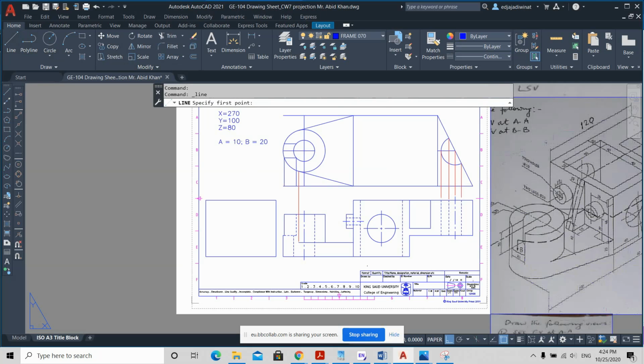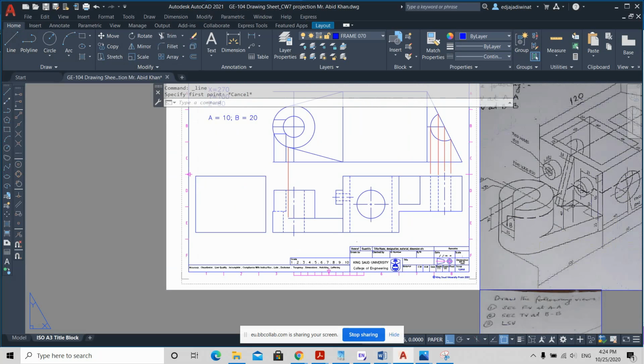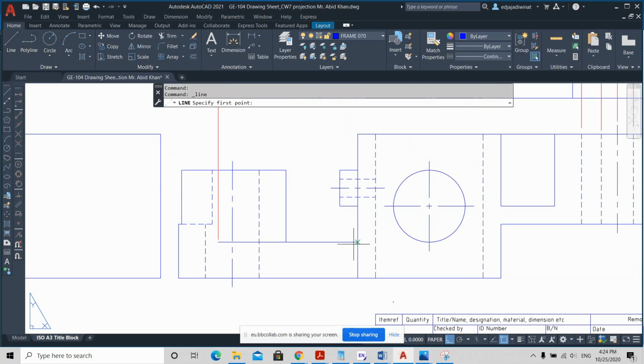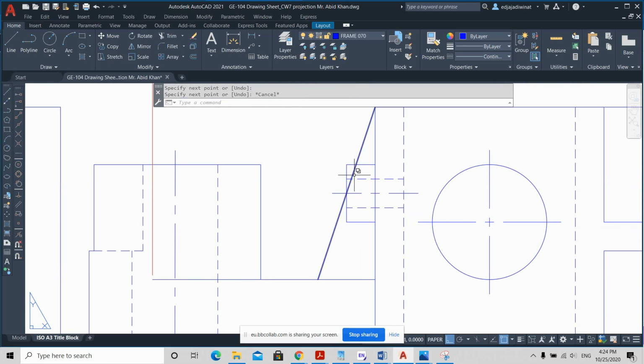And then let us make this a triangle. I'll use the line command from here to a certain point there, and it is 20. Then I'll use the line command again with the extension object snap in the opposite direction, -20, and go there. Of course, this region should be hidden in the middle.